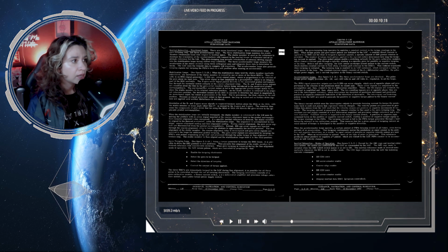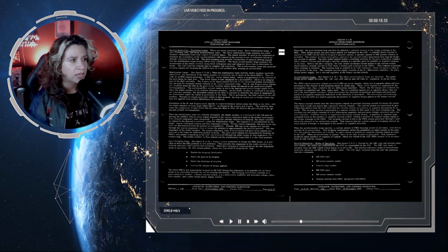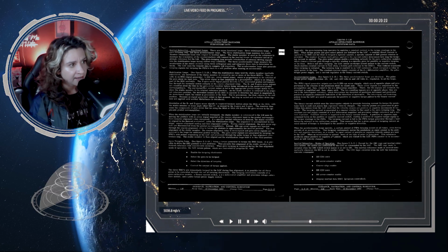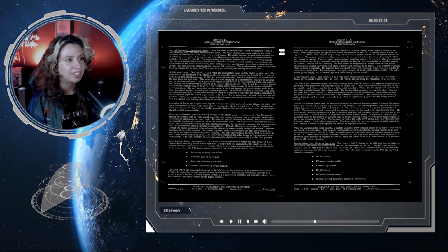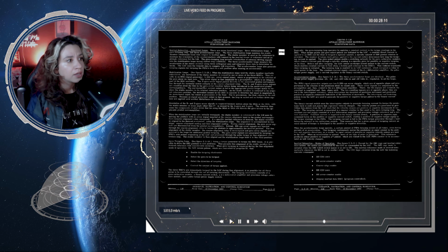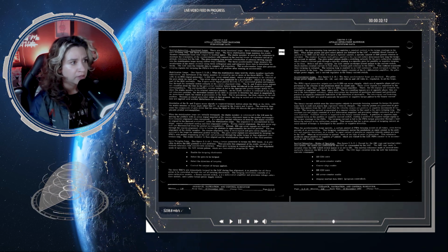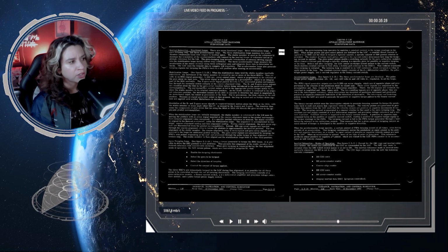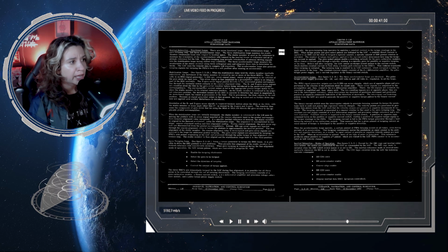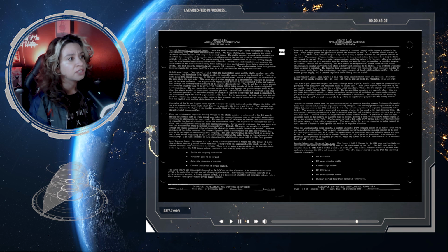Stabilization loops. See figure 2.2-10. When stabilization loops hold the stable member inertially referenced, any movement of the stable member is sensed by one or more of the 3 IRIGs. This results in an IRIG signal generator 3200 CPS error signal output, which is proportional to the rotation of the gyro's input axis. This error signal is then amplified by the preamplifier, which is an integral part of the IRIG assembly.